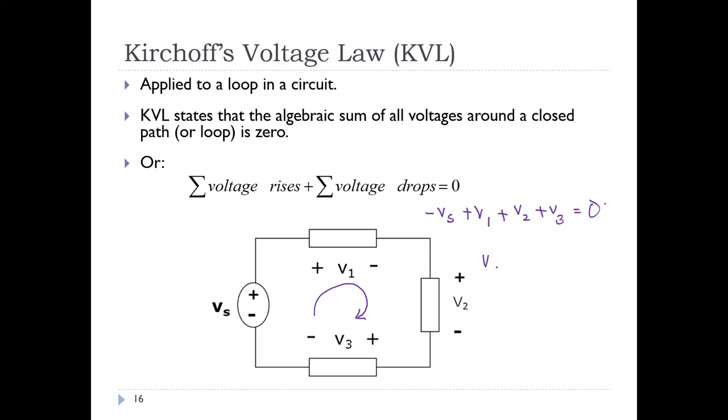So your Vs equals V1 plus V2 plus V3. So if you want to verify whether you are going to get the same answer for counterclockwise direction, okay, let's assume this direction. Starting from Vs also, Vs and then minus V3 minus V2 minus V1 equals 0. Rewriting, Vs equals V3 plus V2 plus V1, which is the same as the upper one.